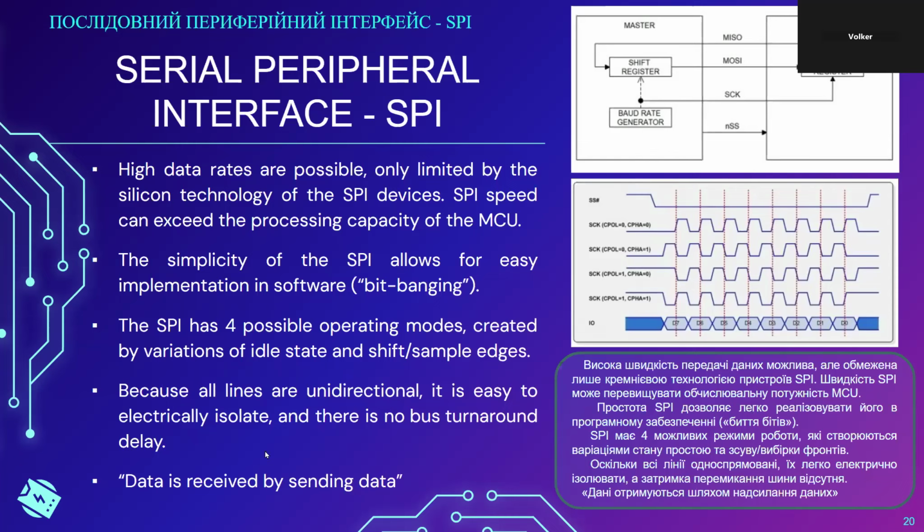So when you are in a subroutine, if you're looking through a code example, and you see a transmission of a dummy byte. The dummy byte could be 0, or the dummy byte could be FF, depending on the idle state of the bus. This is to start a receive process, even though it says it's transmitting. It is transmitting in order to receive data, because the shift registers are coupled.